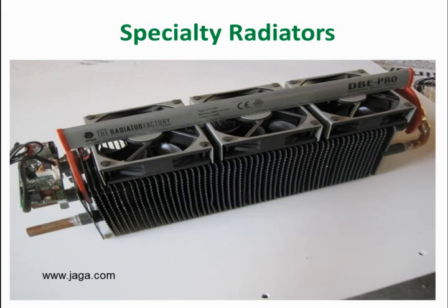Now they've done some other things here that you can see. I don't know what you can see on here, but the fins, they've crimped the fins, they've put them real tight together. They've got big tube or big fin dimension there, the spacing between them. All those things play into the output of a fan coil like that, whether it's a coil on an air conditioner condenser or an emitter for a baseboard. So they've tweaked that, they've engineered that as much as they can to get the highest output, and also the thickness of the fins has a difference in the output of it.